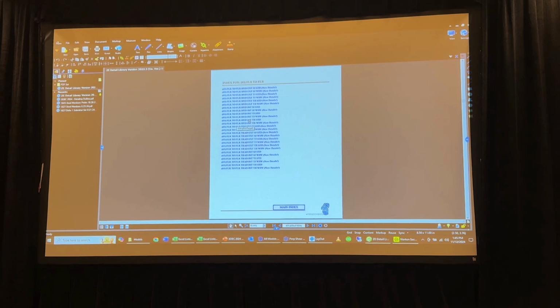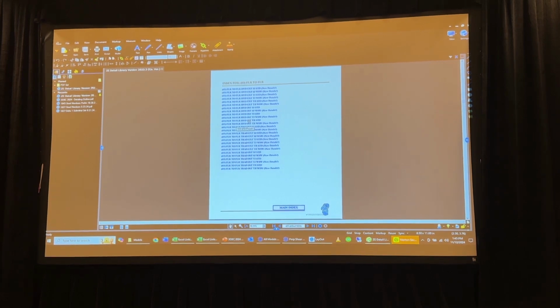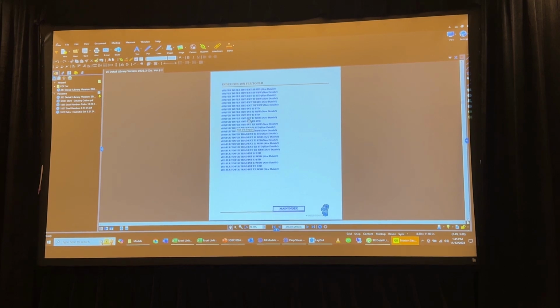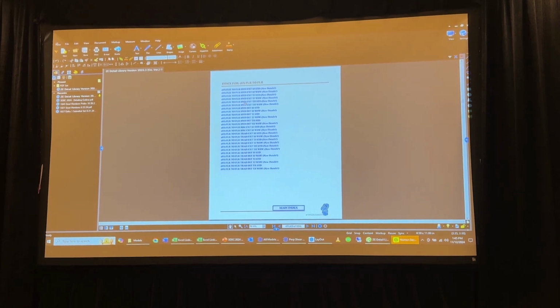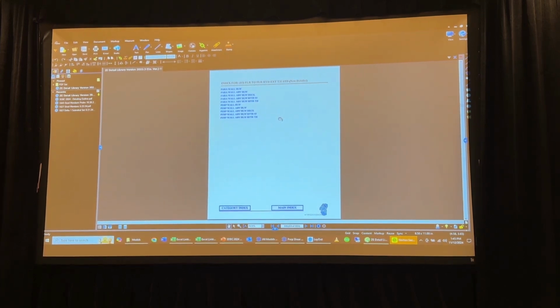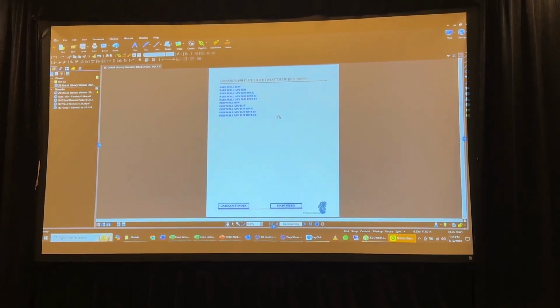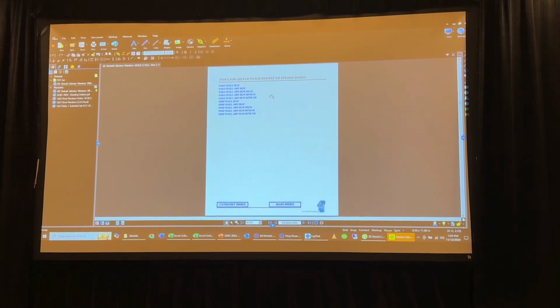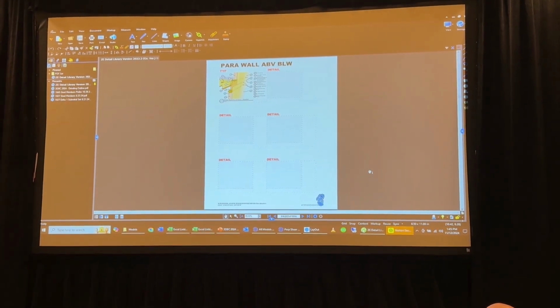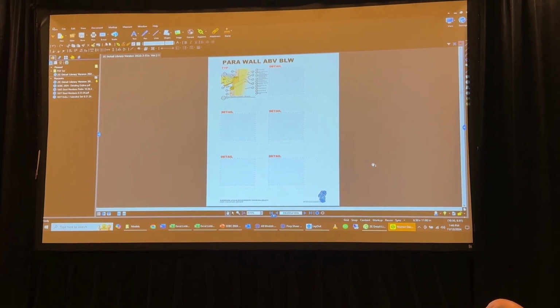And what about interior or exterior? So we've got continuous joists, or we're at an exterior wall? Exterior wall. Exterior wall, okay. Exterior wall, TGI with hydronics. Cool. Now, what do you think? Perp or para? Para, wall above? Yes. Okay, wall above and below. Currently in the library, that's the one detail we have set.